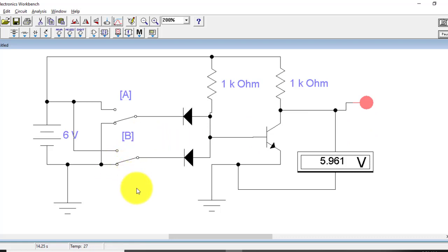As I apply 0 1, I will press the B button and it is on 0 1, and again the output of the logic AND gate will be 0 at 0 1, but after inverting the operation by using a NOT gate, the output is high, and again at 1 0 it remains high, and whenever we apply 1 1, here you can see that the A switch is on logic high and the B switch is on logic high, so we have applied the 1 1 combination and the output is 0. So it's all about the logic NAND gate.